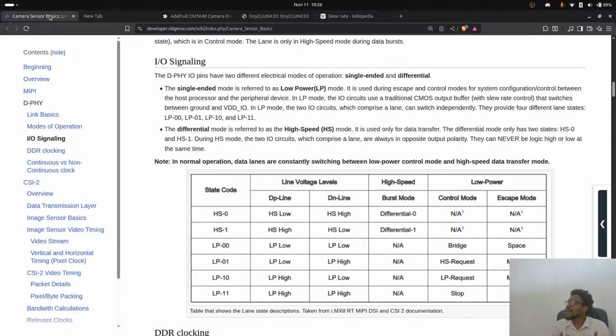But these start becoming ISP, image signal processing things, but they're not necessarily covered in MIPI. But what we do know is they're called control signals. They're control path. This is not where you get the image from. This is where you tell the camera how you want it to make an image for you. So they're not the image one.